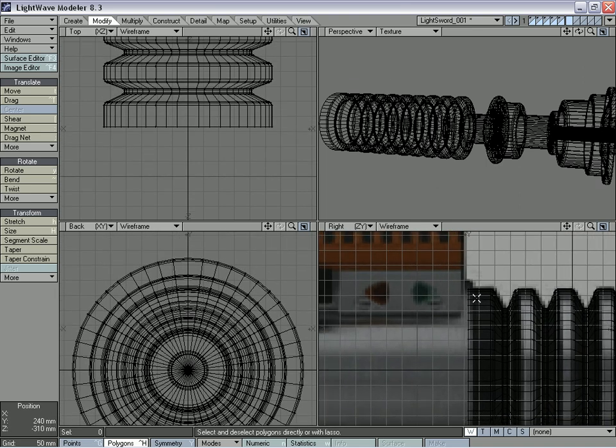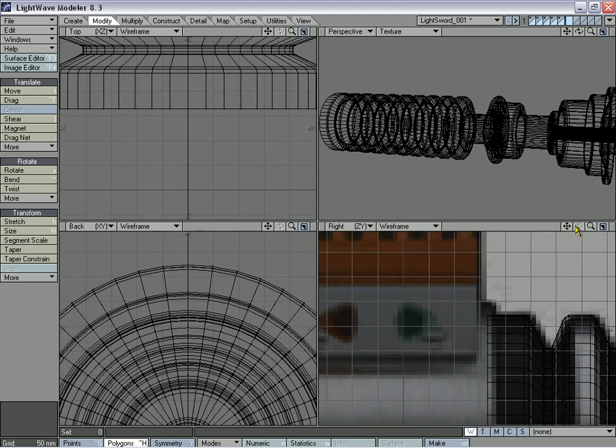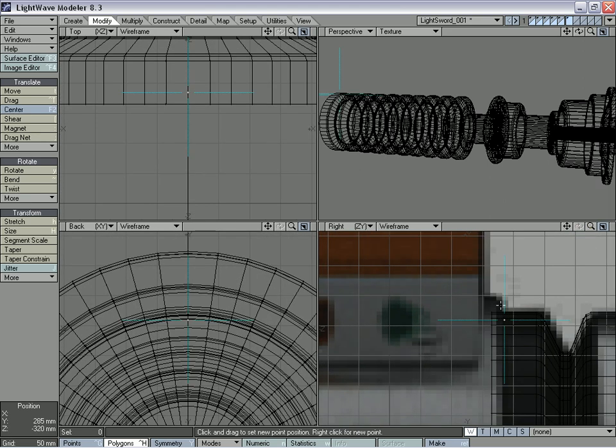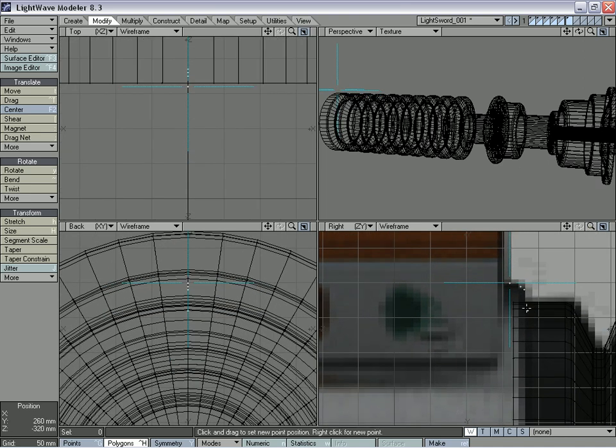Okay, we're going to hit Shift and the plus key to open up our points tool and just start laying these points out, just like we did on the other ones. And making sure that it's inside a little. I'm just using the drag tool right now, Control T.